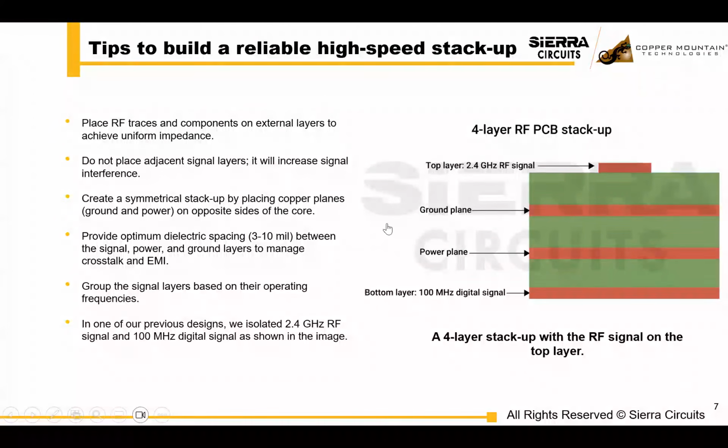This will definitely increase signal interference. So you want to properly create your stack up in terms of placing your ground and power. If you can have ground as your second layer, layer one signal, second layer ground, all the better. And then you want to ensure proper spacing between your layers. And in manufacturing,